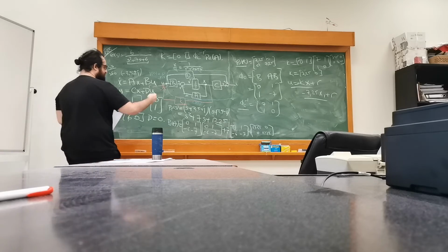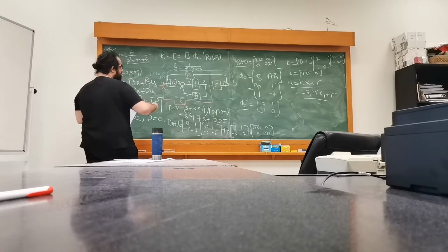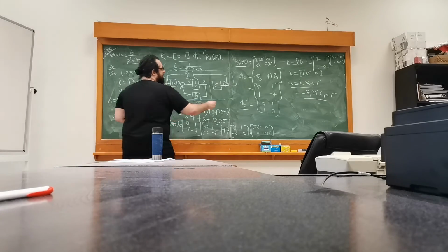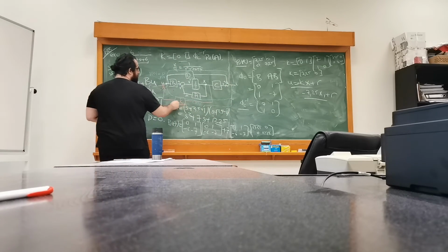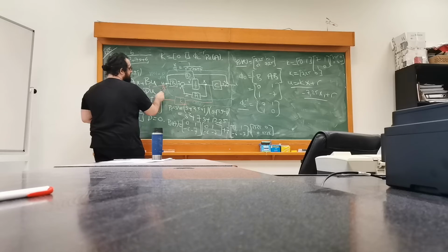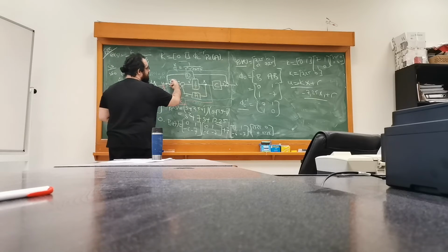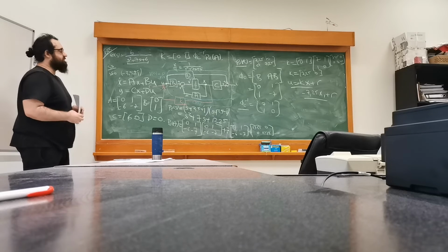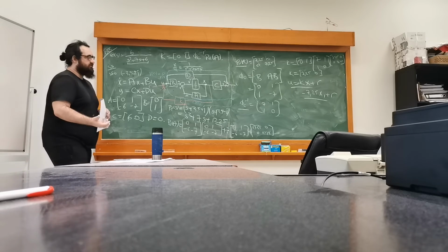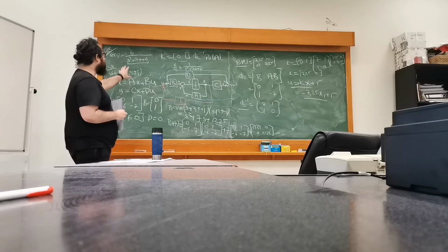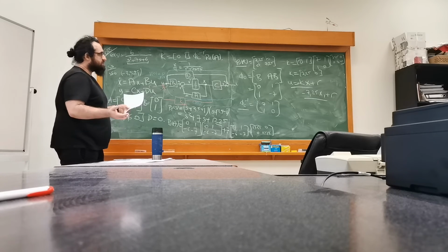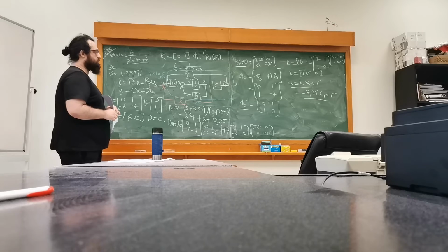We again have a state, and we have a feedback structure, but it looks different because most of the time for classical control, we take the output and the reference and feed that information back. But here we use the states to feed it back, to change the system behavior, to have the closed loop poles like this, and it's quite different than using a p-type controller.